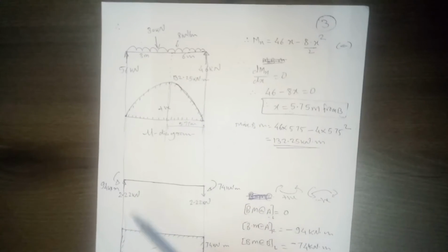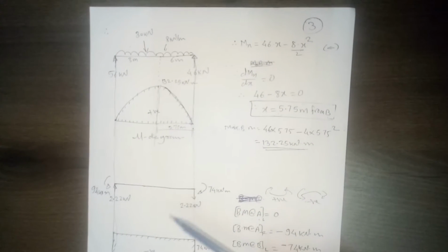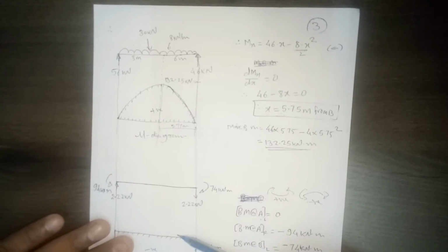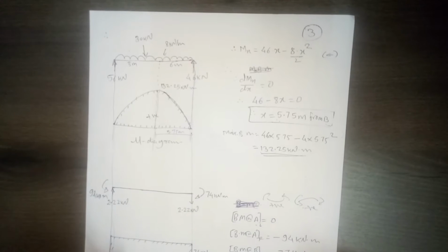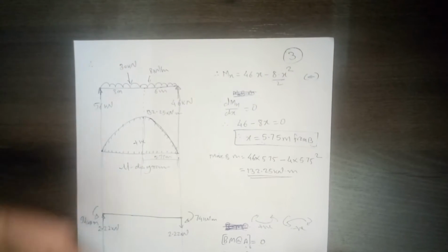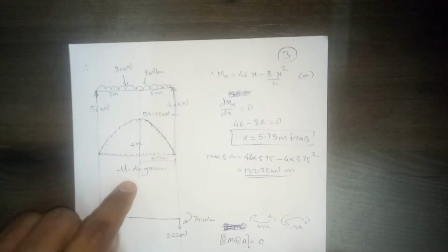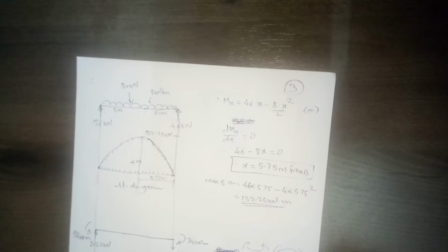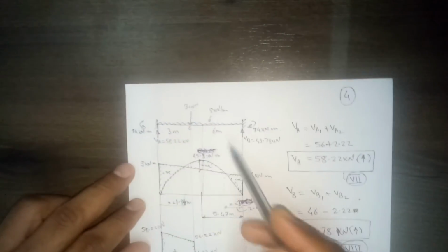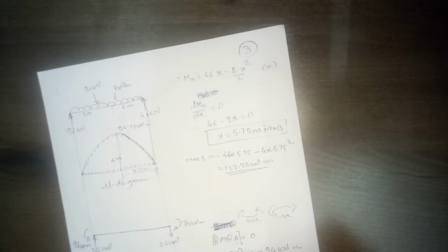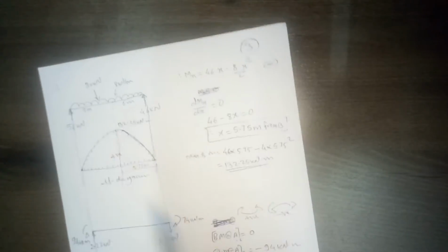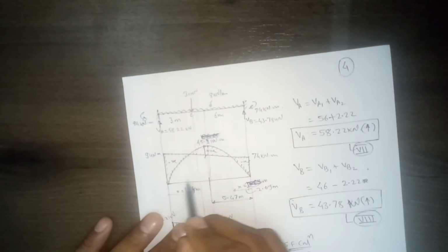So this is like you get two bending moment diagram. Now what we will do, we'll superimpose this mu dash diagram on this positive bending moment diagram, or this mu dash diagram will superimpose on this mu diagram to get the final answer. So for this beam, we have just flipped this moment and overlapped it on this diagram, so then it will look like this.